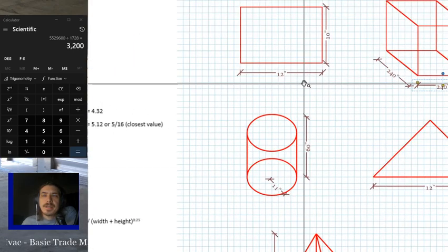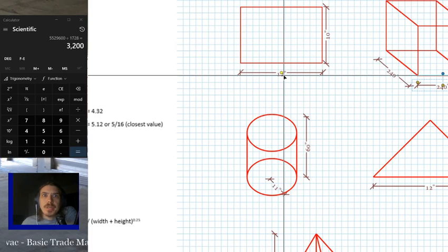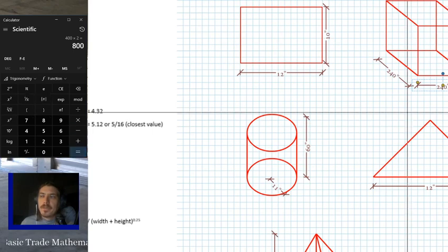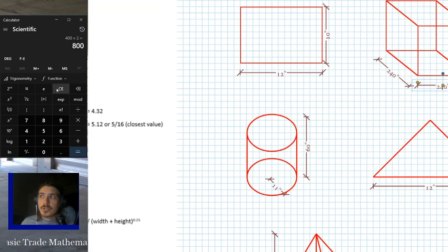So, say we have this 12 by 10 duct and it's the trunk of a 2-ton system. If we're doing 400 CFM per ton, if you don't know, we'll go over it multiple times again later, but 400 CFM per ton is a good middle ground for airflow on the system. So 400 CFM per ton on a 2-ton system would be 800 CFM, right? If a 12 by 10 duct was our trunk, that would be 120 square inches, right?